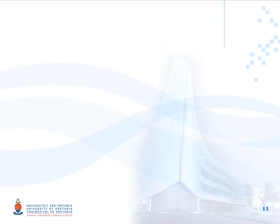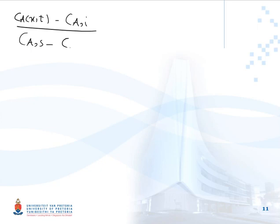So we said that for transient mass diffusion, we have (CA(x,t) minus CAI) over (CAS minus CAI) equals the error function of x over 2 square root of DAB t.